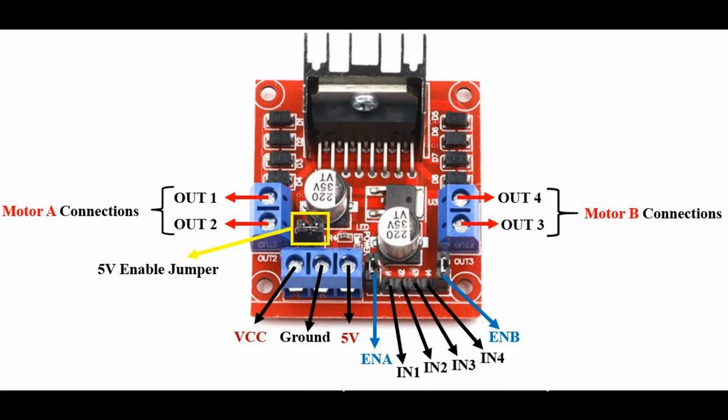B. Vector control, field-oriented control. Function: vector control, also known as field-oriented control or FOC, offers more advanced control by precisely managing the current flow in the motor's windings to control both torque and speed. It involves splitting the motor's stator current into 2 components, one for controlling the torque and the other for controlling the flux.